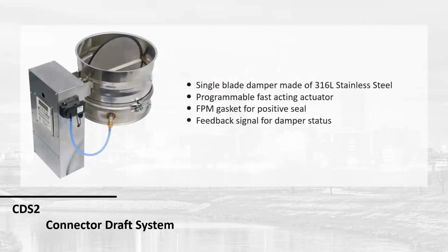And so it assists with light off. It assists with maintenance. It assists with, again, always maintaining that perfect draft. And again, when I first started this, we talked that venting was 90% of your problem. So if I eliminate all of those problems, my venting is always consistently going to be whatever you want it to be at the outlet of the boiler. I've just eliminated 90% of your boiler problems.